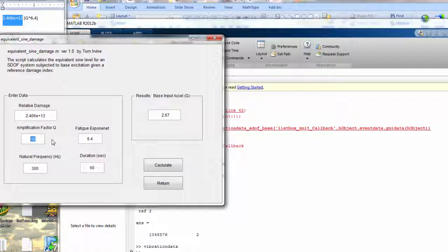It cannot be predicted ahead of time. So there are some reference databases we can consult for typical damping, but for your own particular component or subsystem, whatever it might be, it's imperative you go out and find out for yourself what the damping value is for your system. And just to throw another little monkey wrench in, damping can be nonlinear depending on the input level. That's just another little thing to be concerned about.